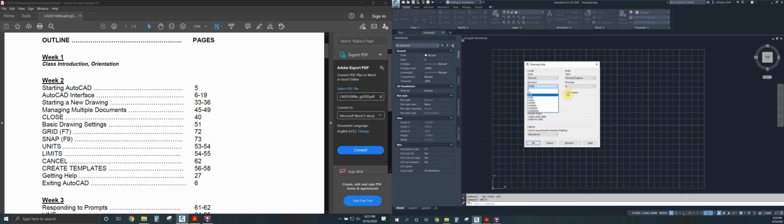And then you can change the direction that it is measuring the units. When clockwise is unchecked, it is measuring like normal units, so it's going 45 degrees this direction. If you click clockwise, it is going from 0 down this way in the clockwise direction, measuring 45 degrees. So you can see here that it's saying 315 degrees.